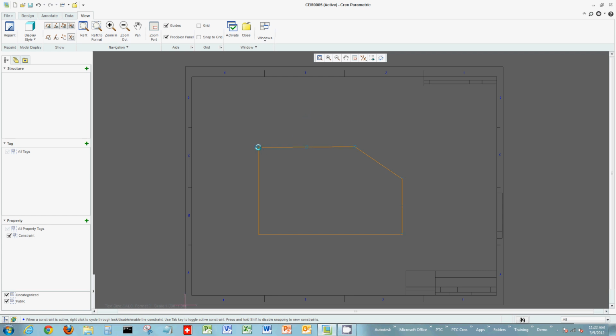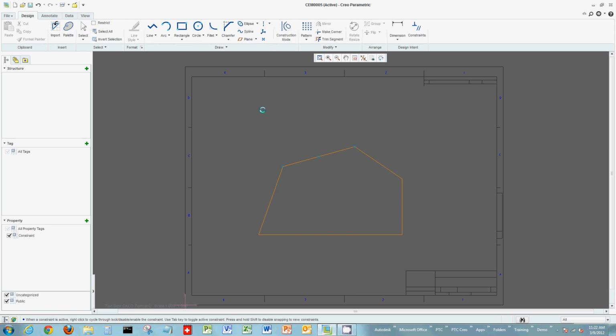You can also select multiple entities and choose to move multiple entities. So I can grab both lines and, moving both lines, I can see these assumptions, these constraints, start to appear when my lines are equal length in this case, or when maybe they're perpendicular, and you can accept those values and move that into that given area.